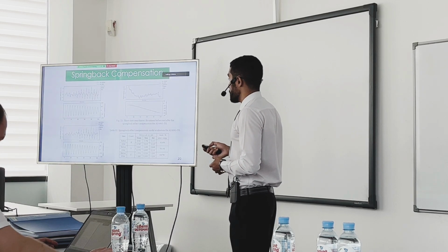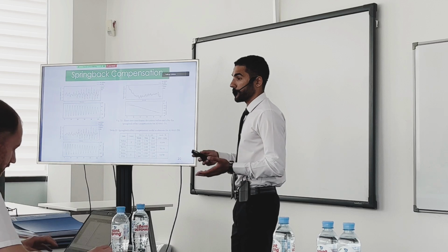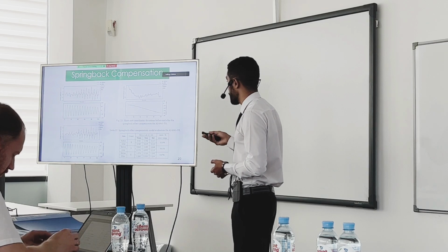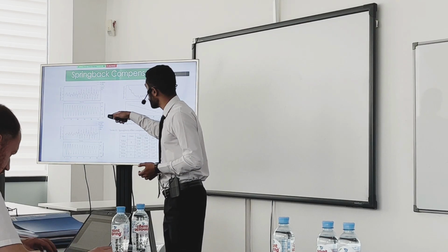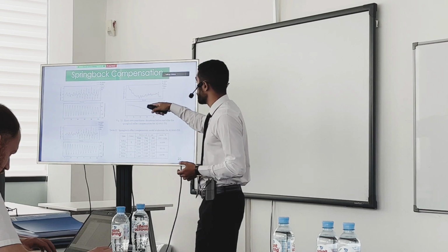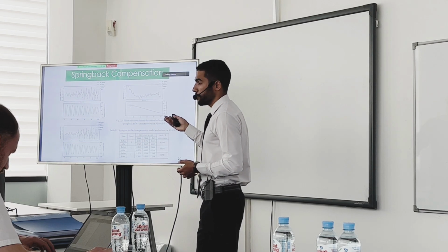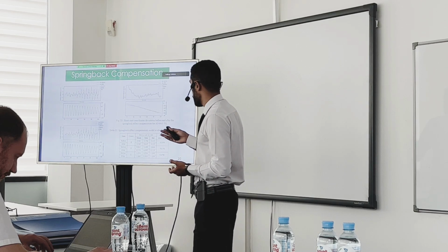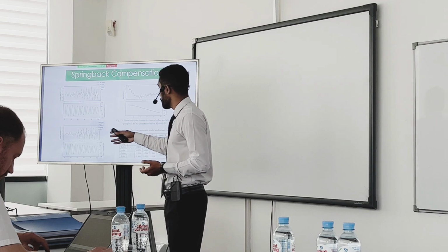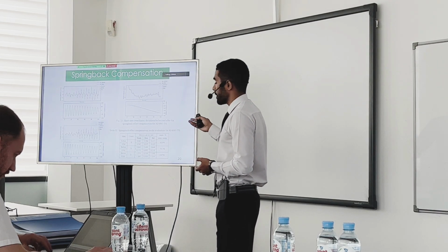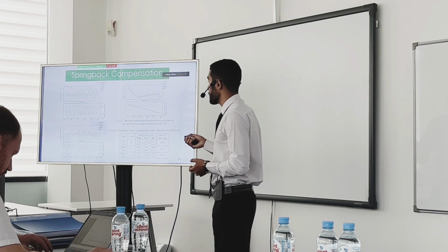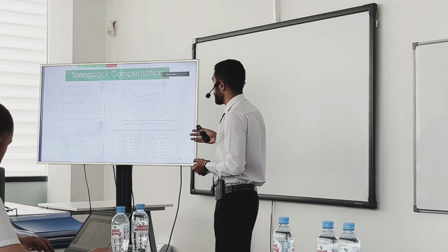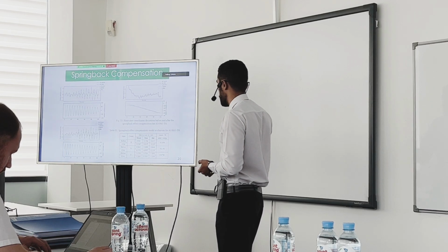The results of this model have been tested for different materials and for different profiles. For example, here are the presented results for the aluminum. You can see in the left top figure that the deviation due to the springback effect has become less by 50%. It's more than 50% actually, and in the Y direction as well. However, in the Z direction, it experienced some limitations, but this was only for the aluminum-like material, and I will show how it acts for different materials.